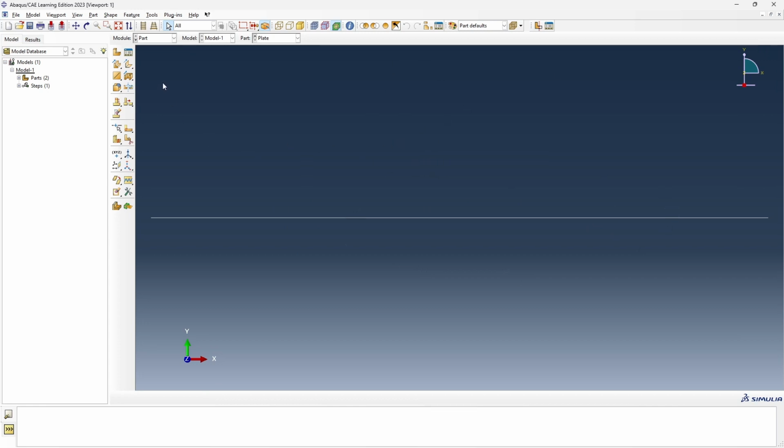Now, how do we attach this line to our hexagon? To do that, we need a specific point of contact, or a representative point, or a reference point. To do that, go to Tools, click on Reference Point, and you see all these little nodes light up. Click on the center one, and that's it. We've just created a reference point.